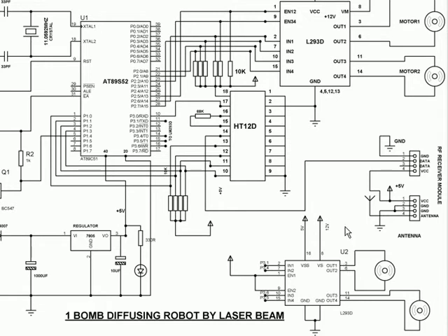And as far as this is the receiver unit, we have a transmitter unit for this also, and in the receiver unit we have a receiving module. It's a 433 megahertz receiving module which receives data in its antenna, serial data, and the data is coming out.